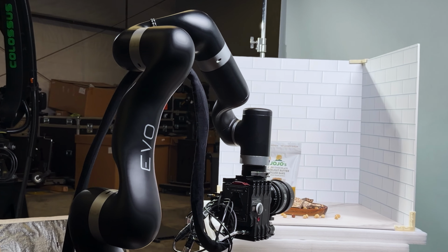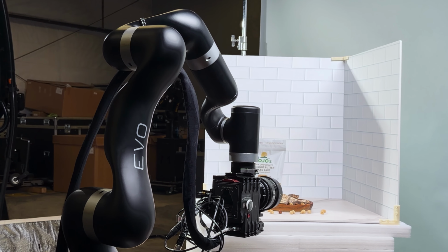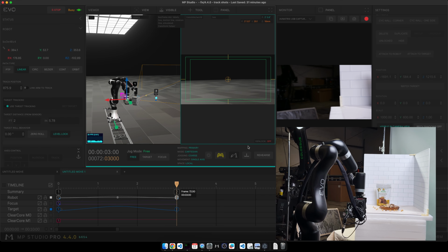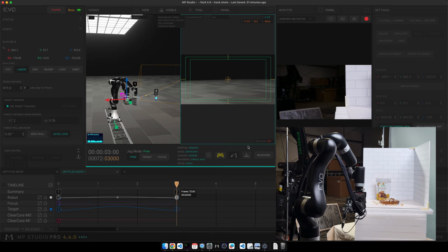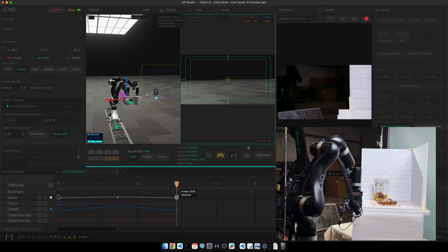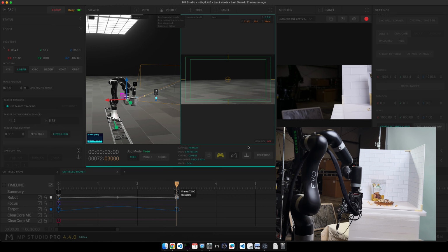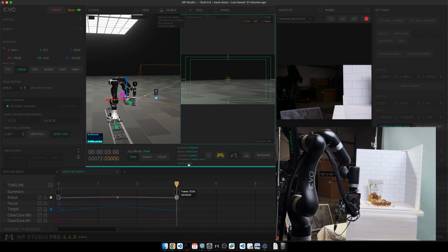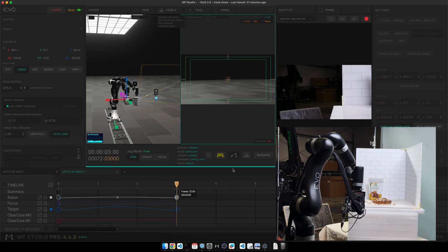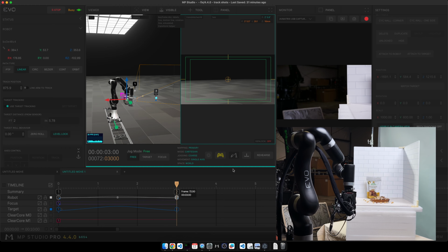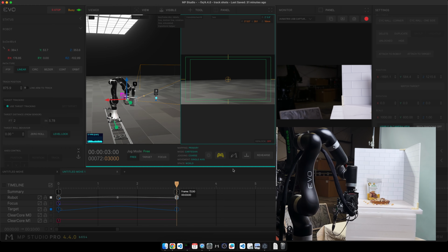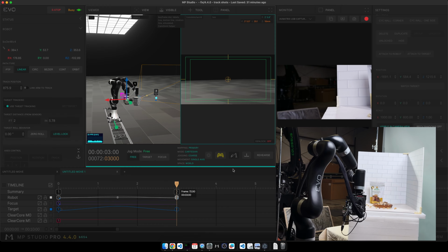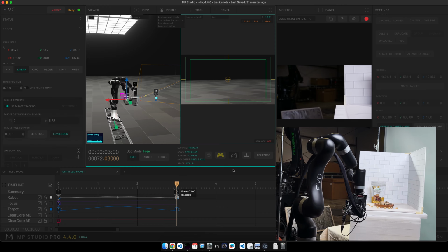You won't be able to notice too much difference in this particular aspect. So if I'm at an angle here and we wanted to show the local, this local in and out would go along the lens path. If I switch to world and go in and out, you see it's moving left to right, because that's according to the XYZ of the robot base. So that's a good example of world versus local.